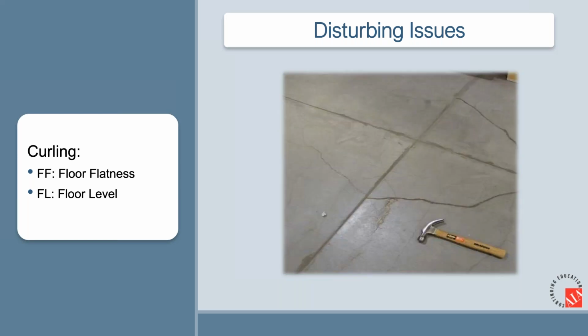And then we get to the bullseye here. Now, while this looks like or appears to be a crack, the crack is simply a symptom or a result of an underlying problem. And that underlying problem here is curling. Believe it or not, concrete is a very unique three-dimensional dynamic object. It is not a two or one-dimensional static object. What I mean by that is you have to address all six sides of a three-dimensional object to ensure stability. And in concrete placement, this is also something we need to do.